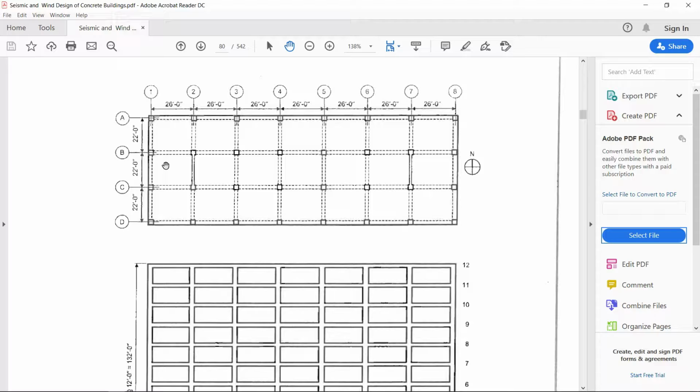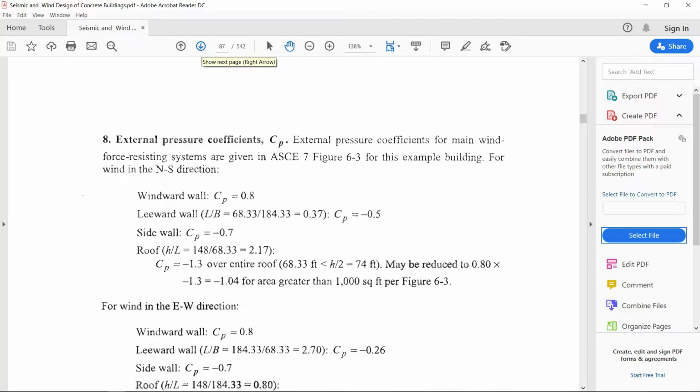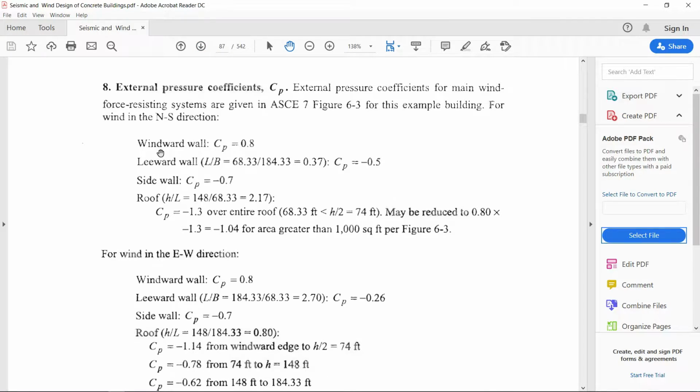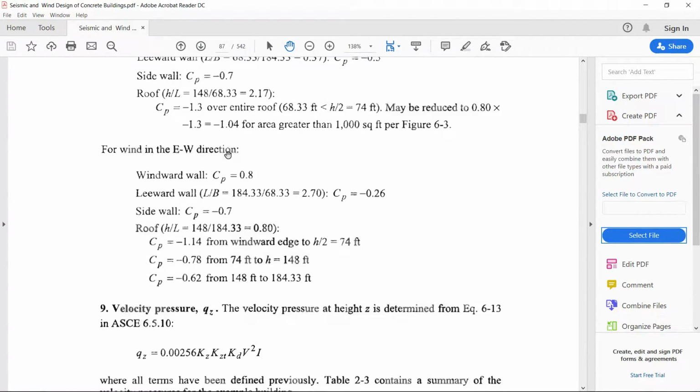So if wind load in X direction is in line with the calculation given over here, we will assume that the wind load in Z direction or in north-south direction will be the same. So it will give us confidence that the wind load generator of STAAD is in line with the manual calculation. So basically this is the idea. Let's proceed. We will go to the procedure to calculate the wind load in east and west direction, which is the X direction for us.